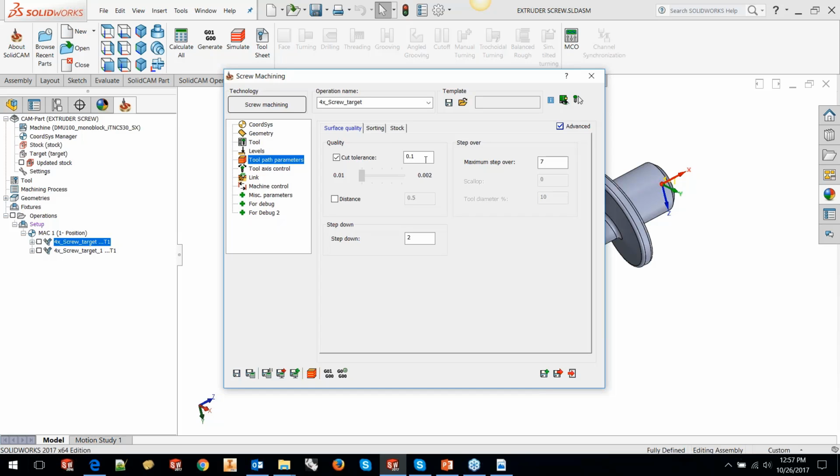It creates an imaginary cylinder, which encompasses the entire part, and slices the cylinder along with the part. Cylindrical slices. If you keep your tolerance very tight, the STL data that is going to be created is going to be huge, and it will take a lot of time to perform the slicing. Since it's roughing, you don't have to keep a very close tolerance. You could keep it at 0.1, good enough.